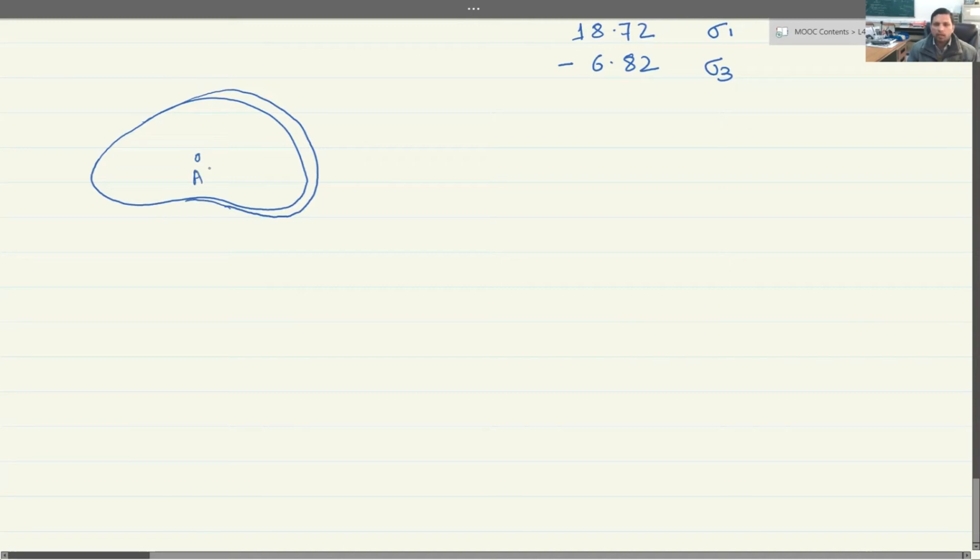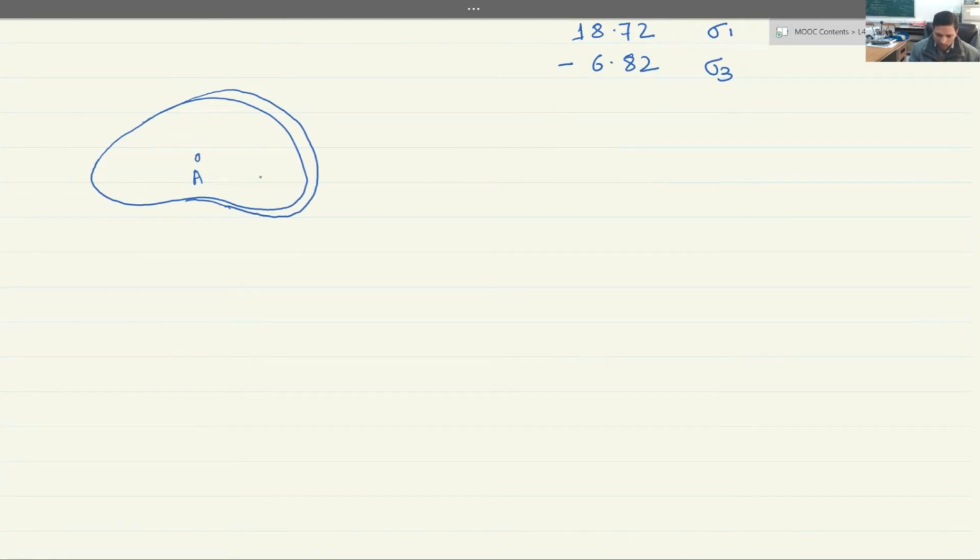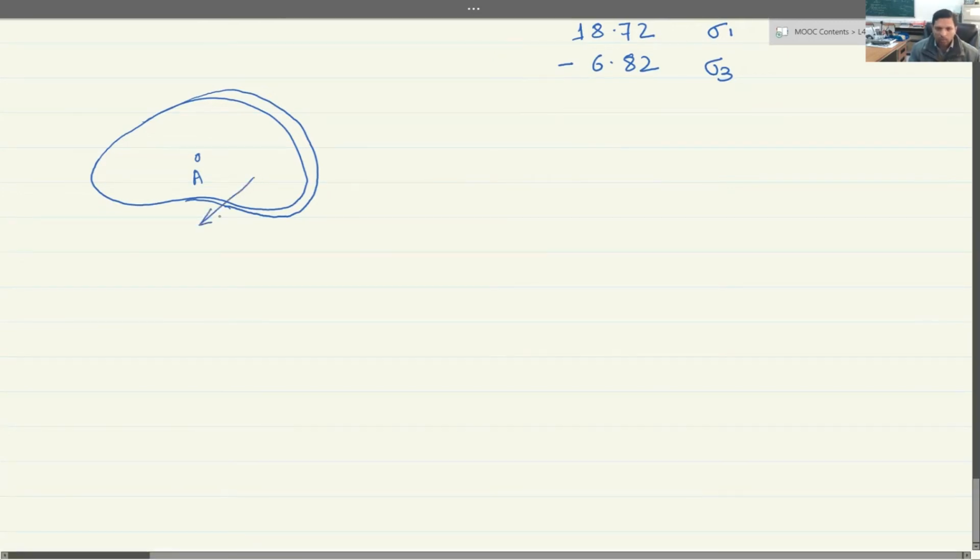As you can see, it is a thin element, and let's assume that there are no shear stresses on the Z side, Z component. So basically, there may be normal stress in the Z direction, but there are no shear stresses. So the condition that you would usually see is when shear stress on one plane is 0.